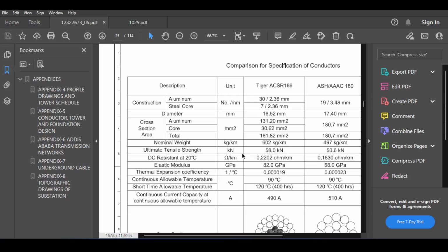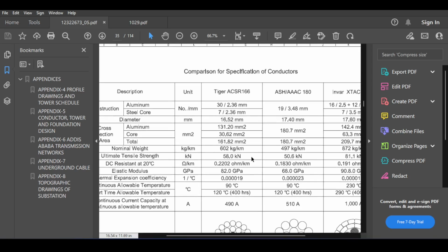which is in kilonewtons. So I'm not really given the working stress or working force. I'm given the ultimate force. Well, it doesn't matter. If I'm given the ultimate force, I will just use it to assume this to be my T in the tension. Some other design sheets might give you something called the F ultimate, the ultimate stress inside the cable. If you're given the ultimate stress, you just multiply the ultimate stress by the area of the cable. So, you can use this to calculate the loads inside the cable.